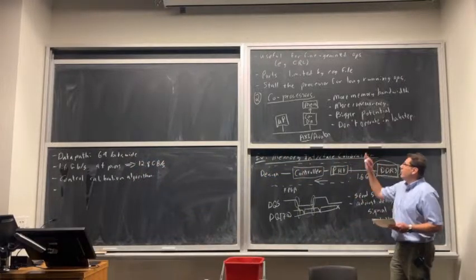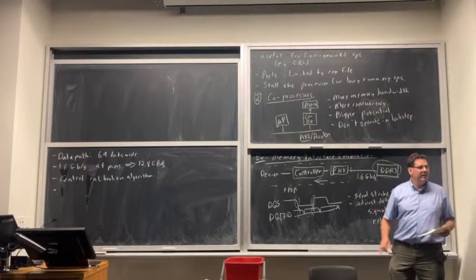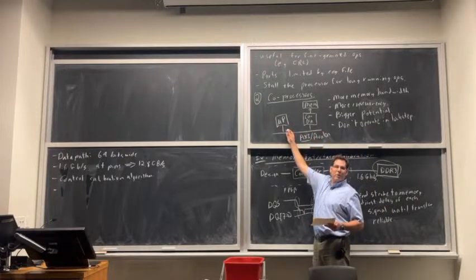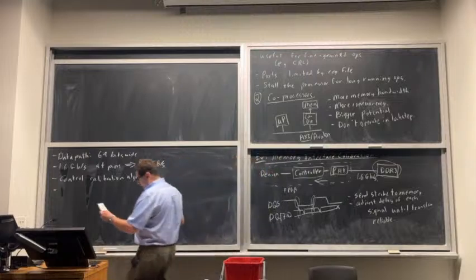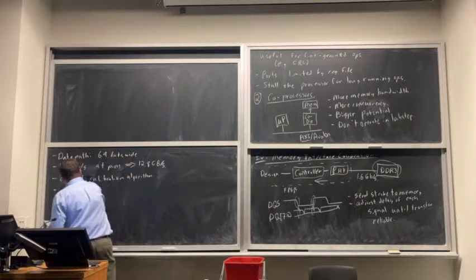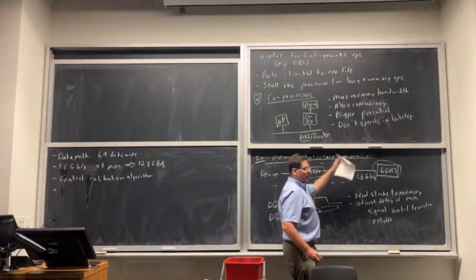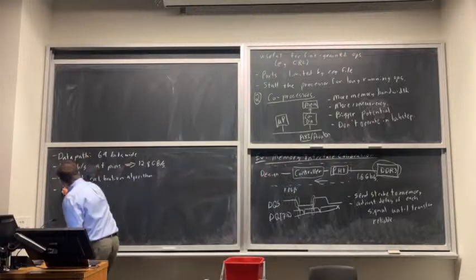So we use a coprocessor to talk to the memory because it's got to talk to it quickly, and you can't have basically a soft or a hard processor, it just can't handle those kind of data rates using instructions. But this control algorithm is really complicated. So it's useful to move a complicated algorithm to a processor. So we use the microprocessor plus coprocessor style.